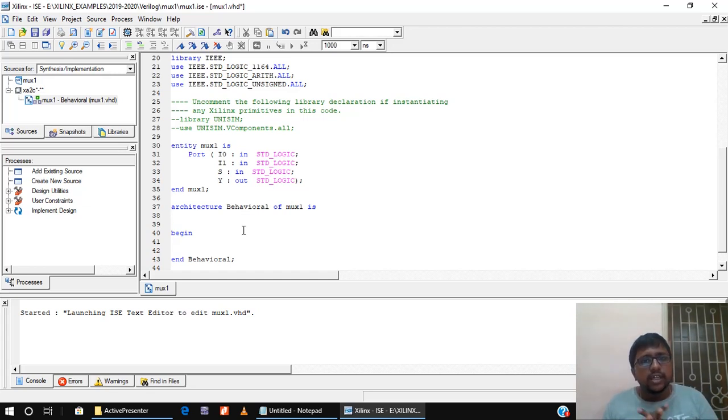So I have to create three different components. A component is always created by using the keyword component, then space. One is AND, but I cannot write AND as it is, because AND or XOR, XNOR, NOT, NAND, NOR, all these are bitwise operators that we use in VHDL. So these cannot be used as an identifier. So I'll create a component called AND1 for AND. Then I have to write what the inputs and what the outputs are.